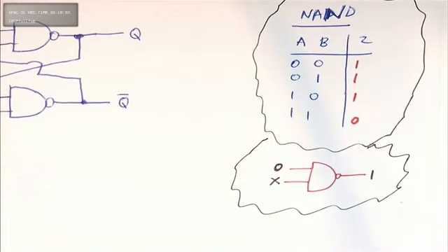The latch is the basic building block, and we're going to repeat it again. We're going to do two things today. We're going to do the SR latch, then we'll do the SR flip-flop. There's something else called the flip-flop. Okay, so is everyone happy with the NAND gate explanation? No matter what your second input will be, the moment one input is a 0, the output will be 1. It will be fixed to 1. Is everyone happy with that? This is a very crucial point.